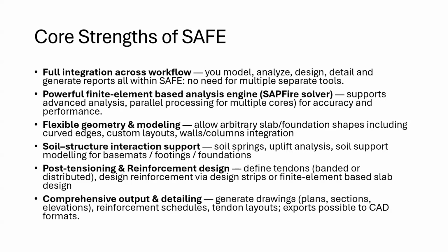So basically the core strengths are the full integration across workflow. That means you can model the finite element model, analyze, design, and you can also perform detailing that can generate drawings. So it is a complete package in that integration of various aspects of your analysis and design.